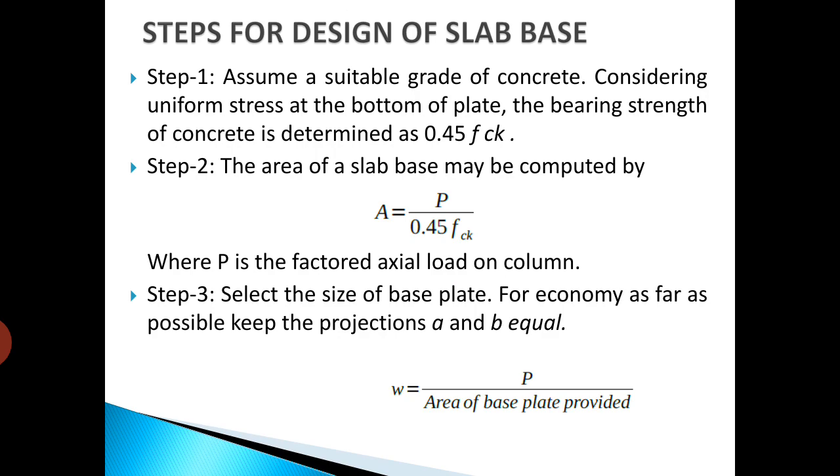Load divided by SBC. So here also, load divided by bearing capacity of concrete, where P is the factored axial load on the column. The P is given as the load acting on the column. Then step 3 is to select the size of the base plate.